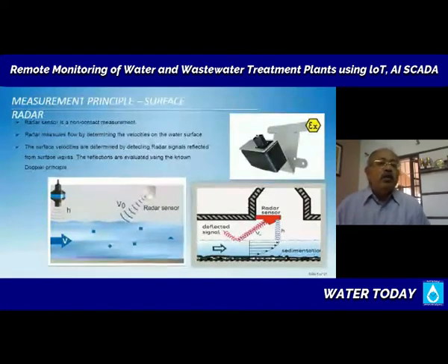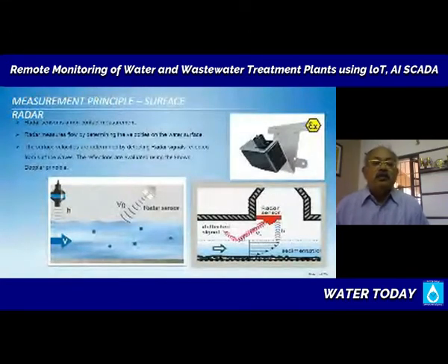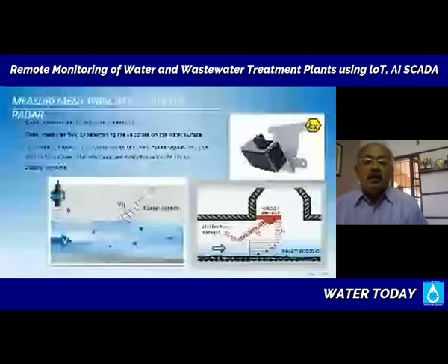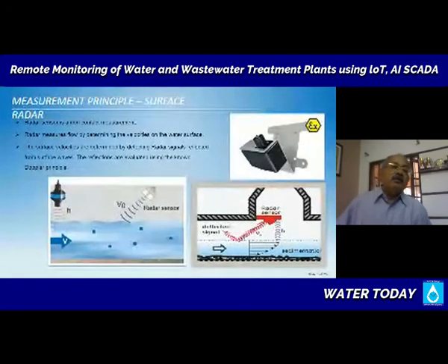Now, moving on, we saw the ultrasound signal and the cross correlation signal, and this is the radar device. Radar technology is very well advanced now. Recently, I installed some sensors in irrigation canals in Gujarat. These measure the surface velocity of water quite well, and also measure the depth of water flow. Then, knowing the velocity and the depth, you can calculate the volume flow quite efficiently.